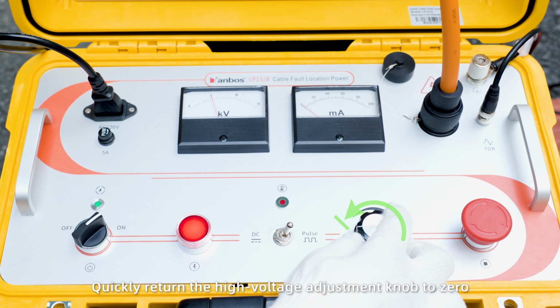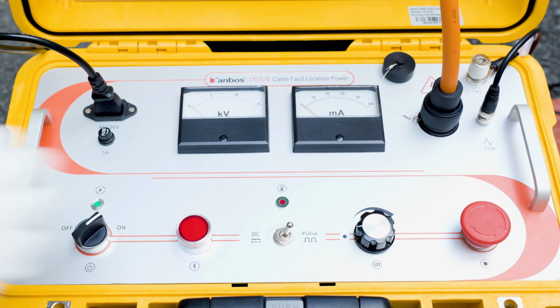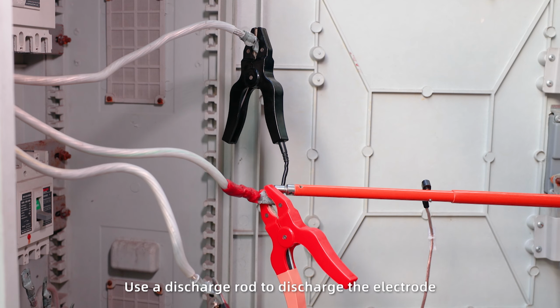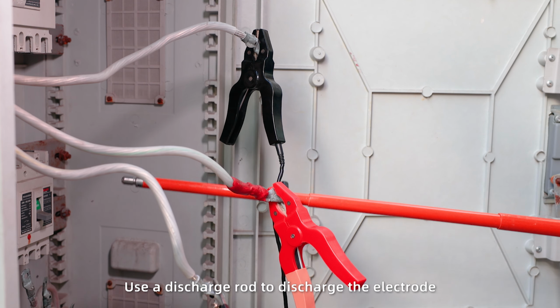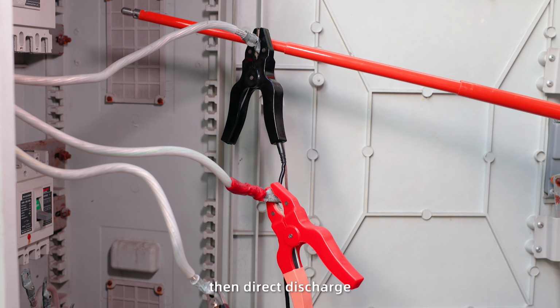Quickly return the high voltage adjustment knob to 0. Press the stop knob. Turn off the power switch and remove the power supply line. Use a discharge rod to discharge the electrode. First perform group discharge, then direct discharge.